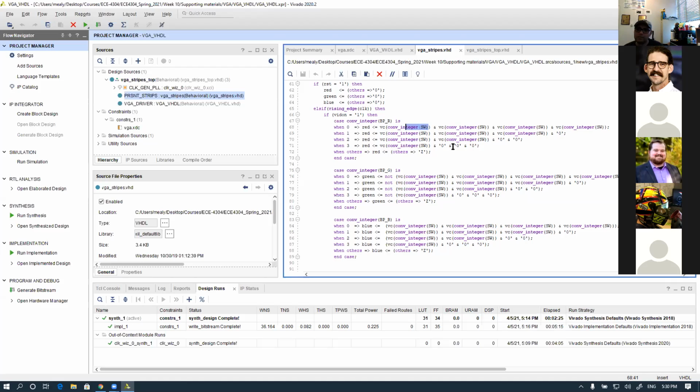Can somebody tell me an idea? How can we make it reconfigurable? I think that would have to do with the sync characteristics that you get from the monitor. There's a handshake that the monitor sends out that says, "Hey, this is my native resolution, and I can support these sort of things." Yes. If you don't adhere to it, then it's going to look weird.